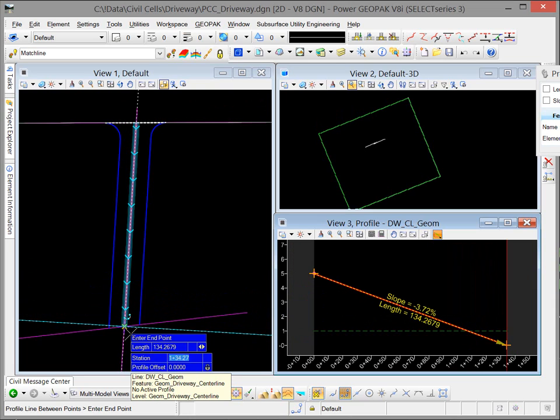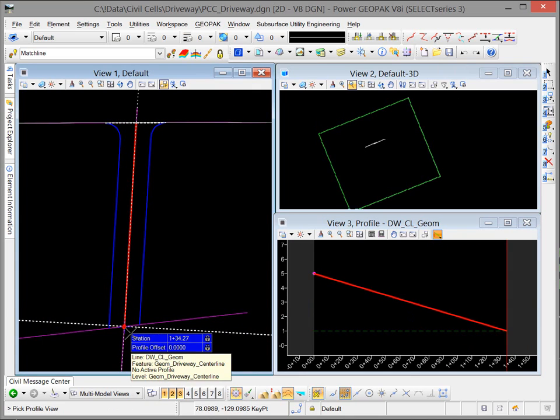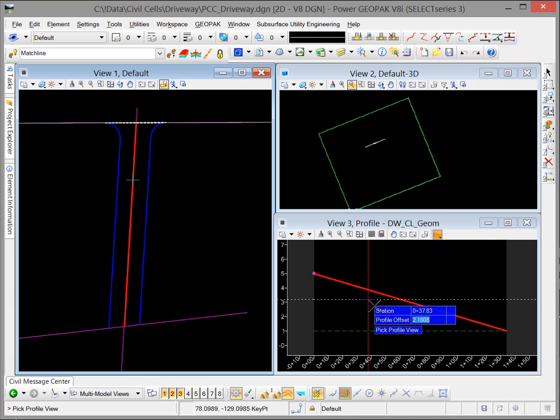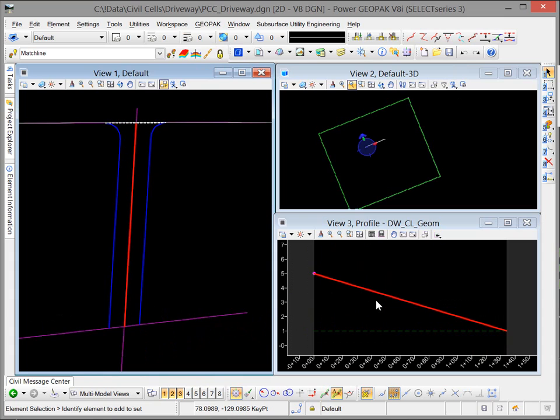You must do a MicroStation tentative snap. So I'll do a tentative, and then a left mouse button to accept, and accept again. I can exit out of the command by hitting the escape key or F4 in the examples workspace, or choose none. And now we have this profile that is locked to the main edge and it is locked to the active terrain model.